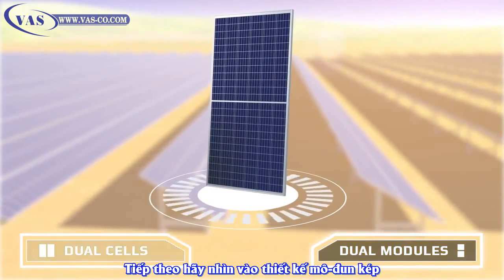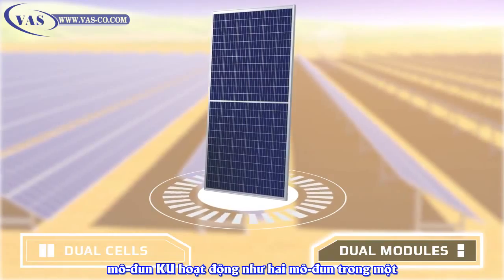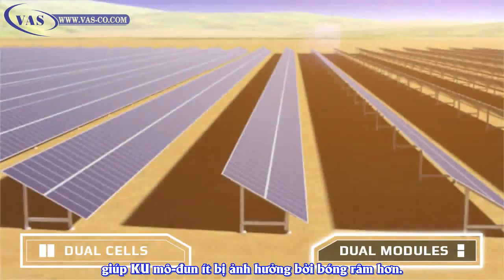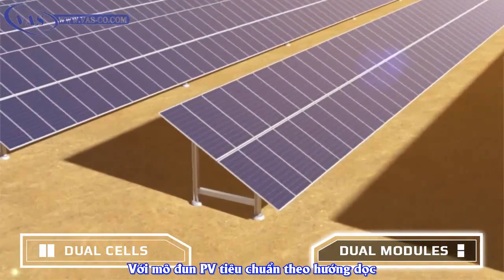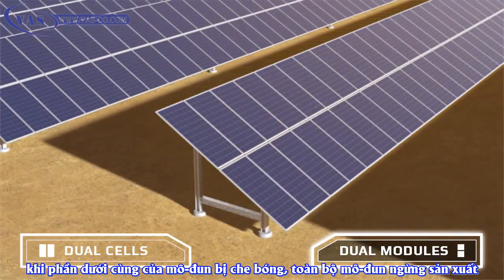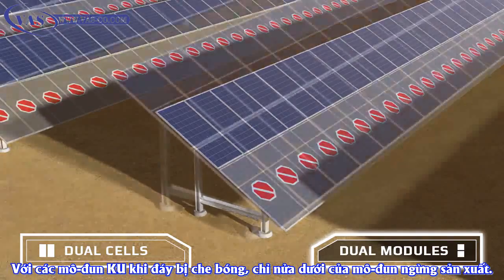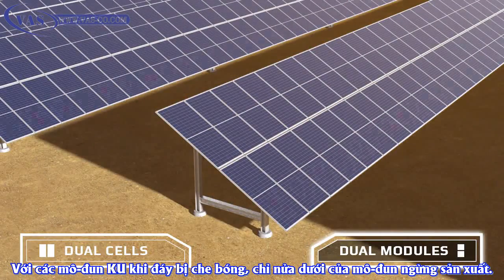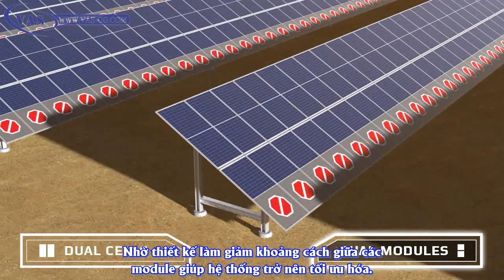Next, let's look at dual module design. Ku modules operate like two modules in one, which gives Ku modules better shading tolerance. With a standard PV module in portrait orientation, when the bottom portion of the module is shaded, the entire module stops producing. With Ku modules, when the bottom is shaded, only the bottom half of the module stops producing. This allows you to optimize your system design for tighter inter-row spacing.